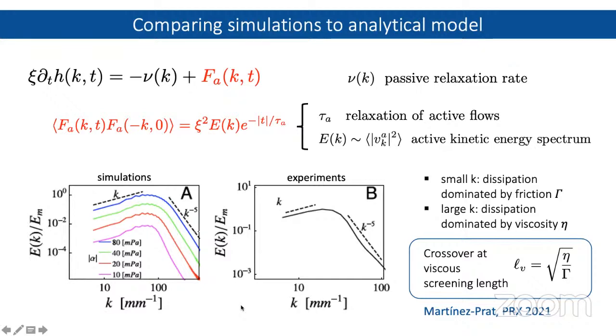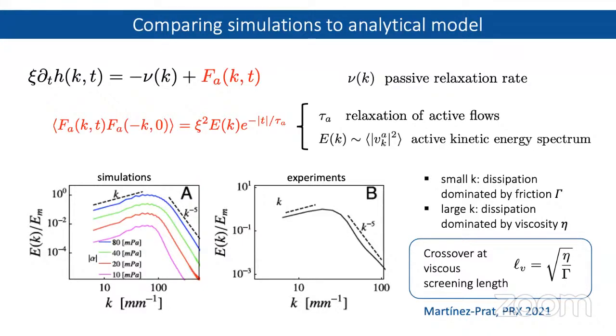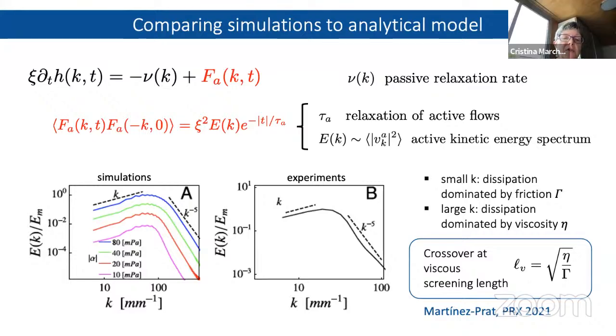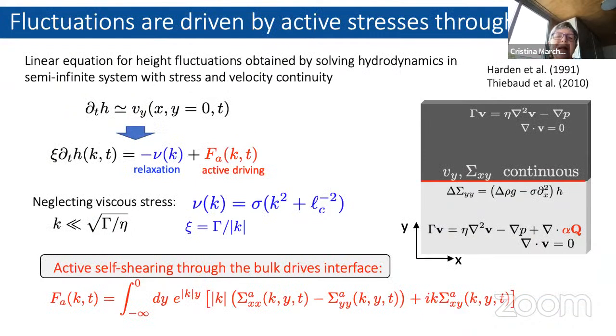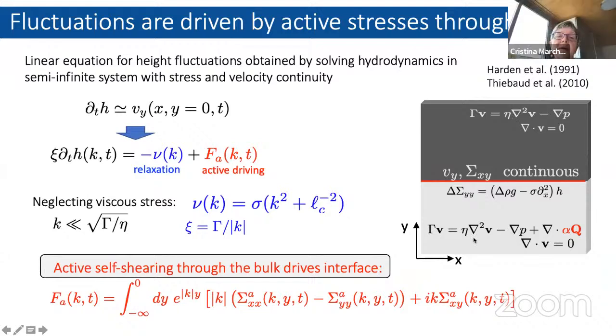Okay, so if we change the medium to air, let's say, will it not change the system overall? Well, okay, our calculation is a bit of a cheat here. This is a pretty lengthy calculation. Our calculation was done assuming the viscosity of the two media are the same. You see, we have the same eta here. Okay. That's certainly not the case.